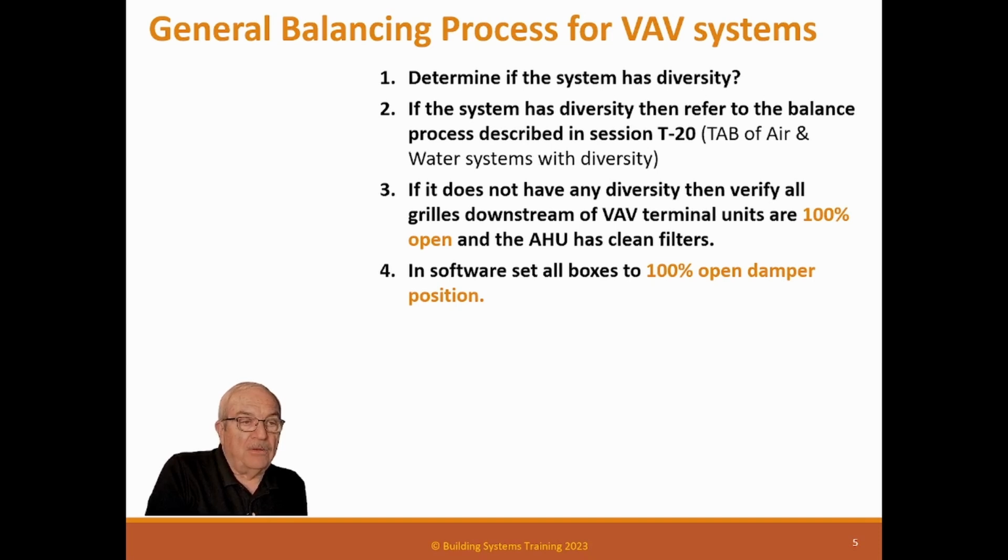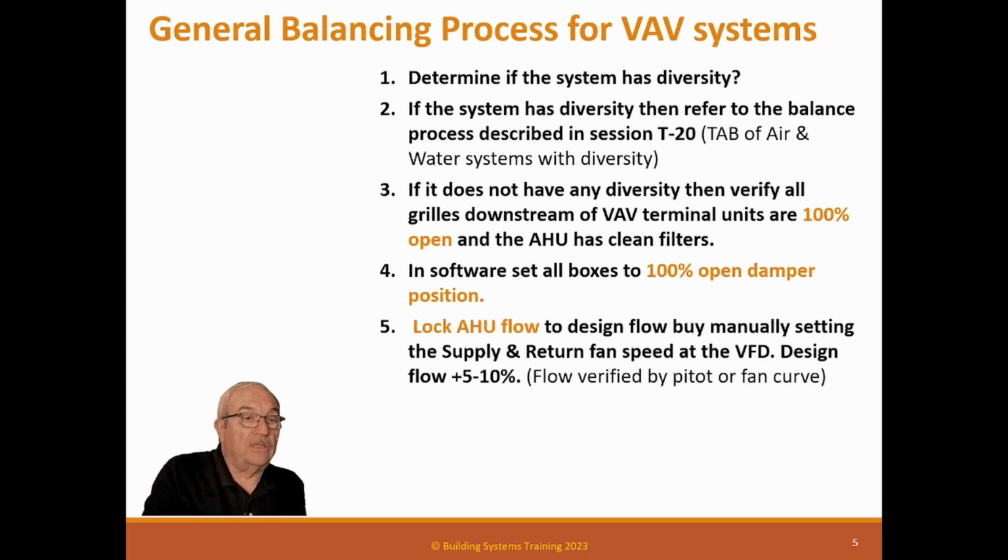But I don't recommend that way, because if something changes, say the general contractor gets real irate because it gets too warm in the space and he makes somebody change that temperature, now your system's on automatic and it screws up your balance. You don't want to do that. Remember, we're trying to balance full flow of the air handler to full flow in the field at the same time. We don't want anything on automatic. We want manual to do that.